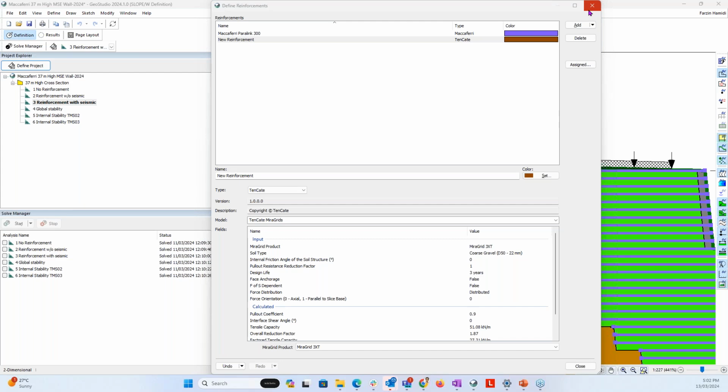So it reduces the suction strength by saturating that area, so you won't have any suction strength, and it will substantially affect your SLOPE/W results if you consider the suction strength in your temporary construction stage. We typically suggest not to incorporate suction in a long-term stability analysis, because when you have heavy rainfall, you might lose it.